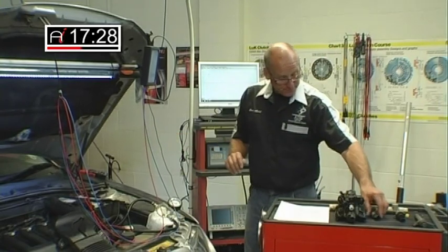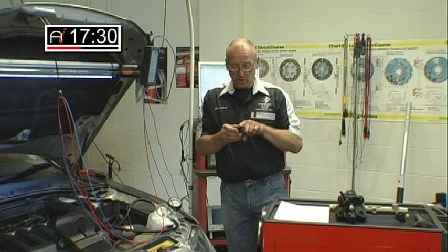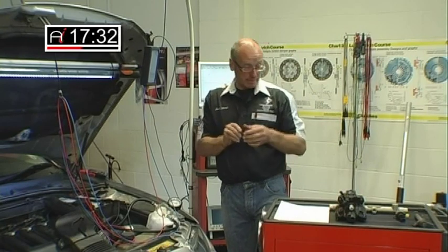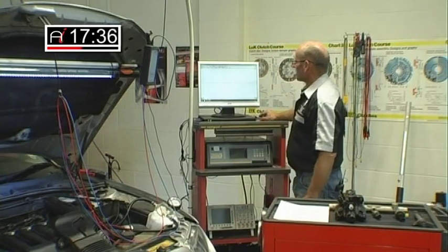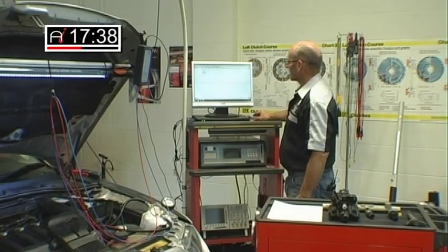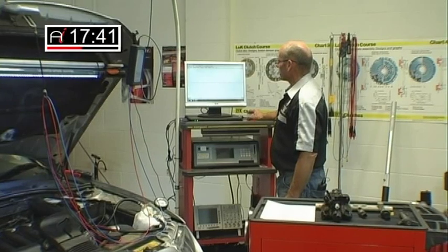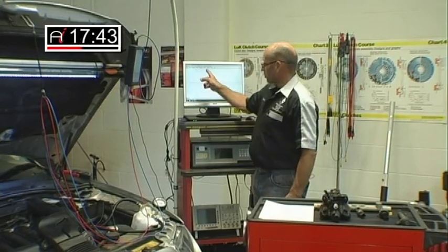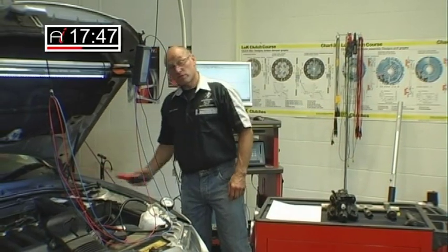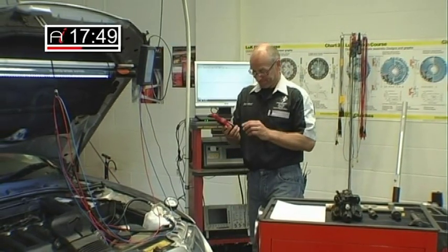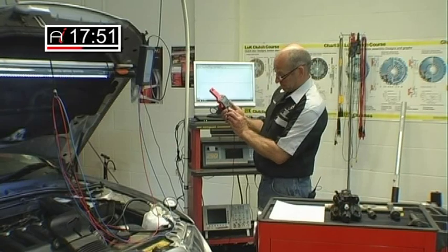Channel 2, red, is on the middle pin of the rail pressure sensor. Voltage, and it's a 5 volt device, so I've set a 5 volt range. Current, I've not yet set up. Now we use voltage for current, it's quicker and more practical.